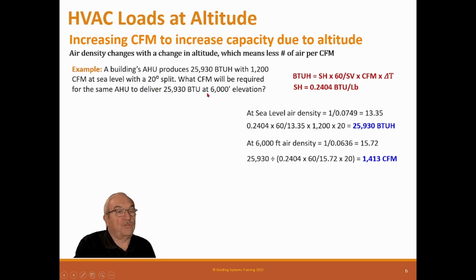And then we have to make sure the coil in this unit is capable of handling 1,413 CFM at a reasonable pressure loss so that the system doesn't falter. If it's a package unit, we're going to have to go from a 3-ton up to 3.5 ton to get the right amount of air. So that's how we're going to have to change that to get there.